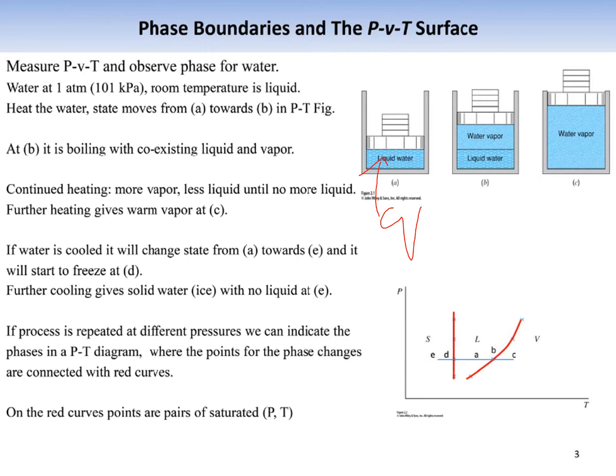Now, when water starts boiling, its temperature will remain constant at 99.6 degrees centigrade. However, now its volume will be increasing because vapors are being generated at a high pace. So the piston cylinder assembly will grow in terms of size, up to when all of the liquid is converted into vapor.